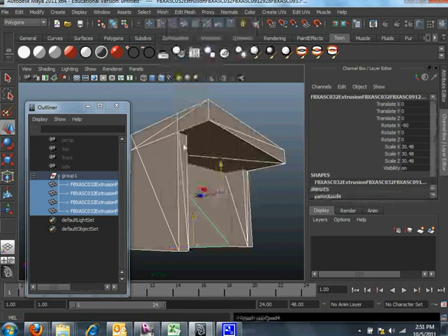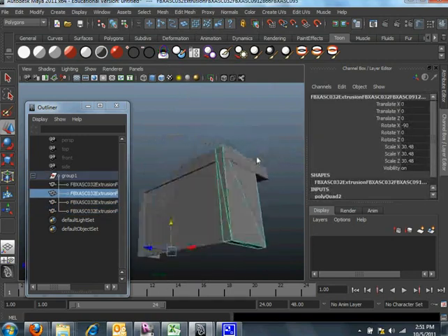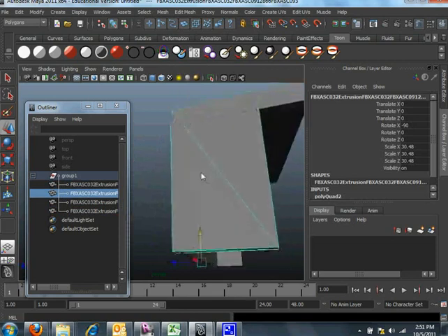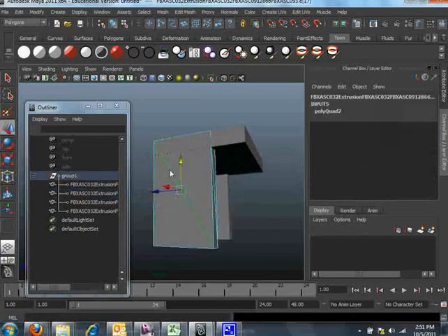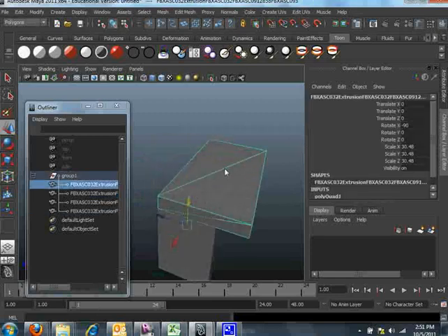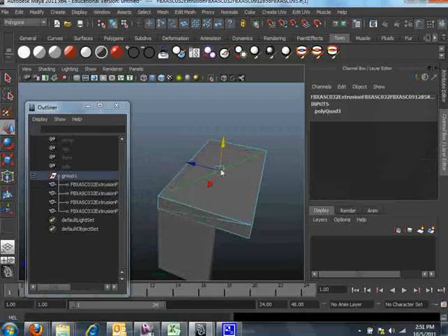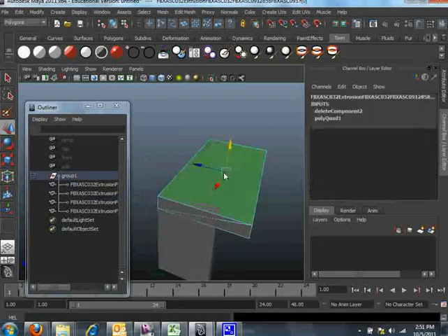So I would do that. It doesn't really guarantee it will work. It works for some faces, but not every single face, which sometimes you have to manually select the edge and delete. That is not really good. So you can select that edge and delete. The goal is you want to have a clean model. This is one single face, and then when you move, you see the update.